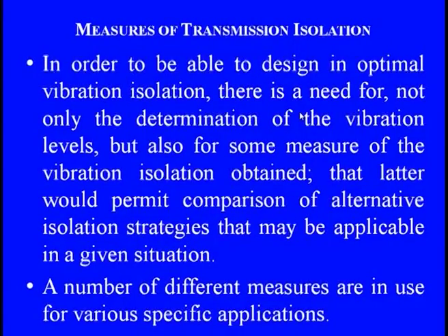It would be easy to find out what exactly the frequencies are, and according to a low frequency, natural frequency meaning the resonant condition, or a higher frequency, we can adopt the isolation strategies accordingly. And in the corresponding way, we can choose what type of spring material to use, so that we can provide the spring stiffness correspondingly.